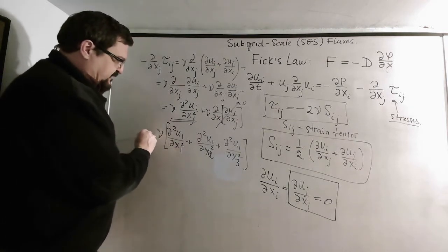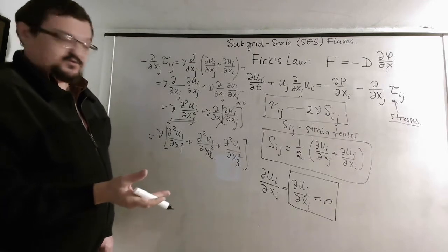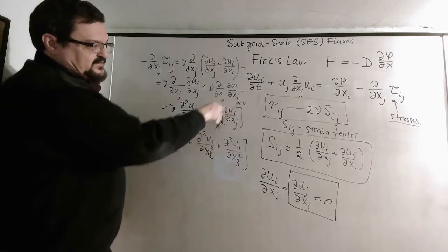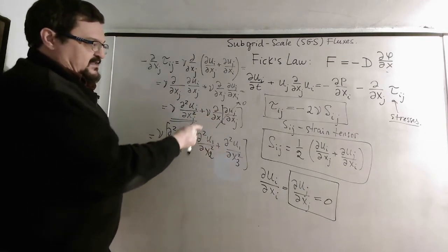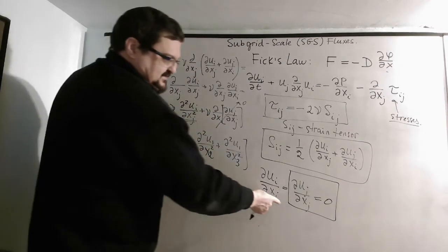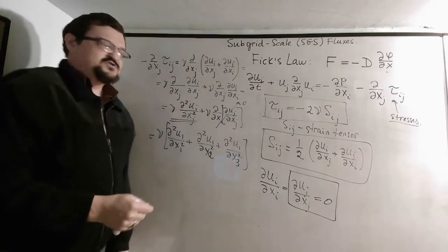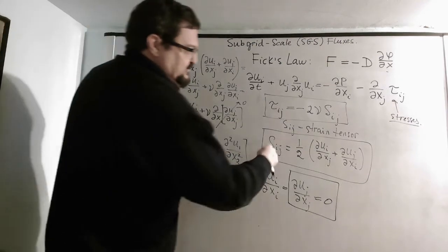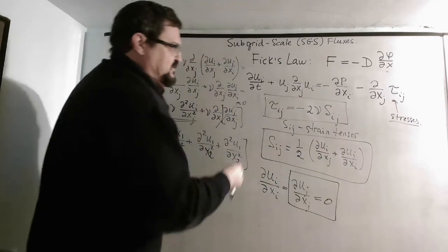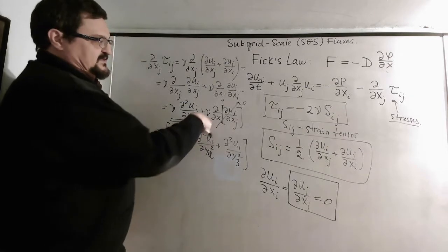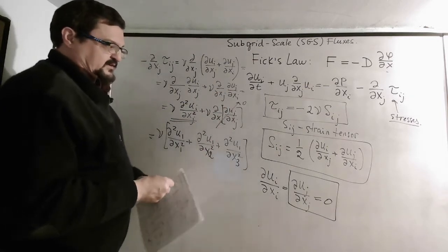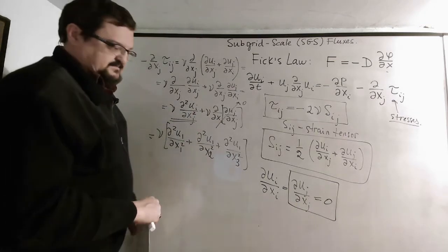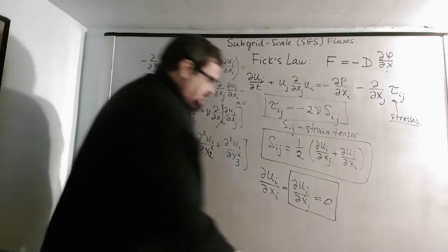So this looks like the normal diffusion operator that we're used to, but again, you see, even though it's like that, it's only a consequence of our divergence being equal to 0. So that's only true in this case. When divergence equals 0, then we can write in this form, technically speaking. Other than that, we need to use this definition and not cancel this term, because it's for a compressible fluid, for example. This term is not cancelled. Okay, but that's a little detail.